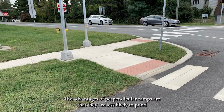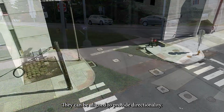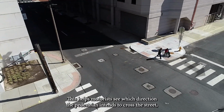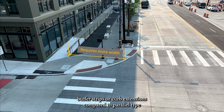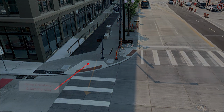The advantages of perpendicular ramps are that they are less likely to pond and trap sediment because the turning space is at the top of the ramp segment. They can be aligned to provide directionality. This helps motorists see which direction the pedestrian intends to cross the street, increasing safety. The disadvantages of perpendicular ramps are that they require wider sidewalks, buffer strips, or curb extensions compared to parallel type ramps, and large radius corners can present directionality challenges for designers.